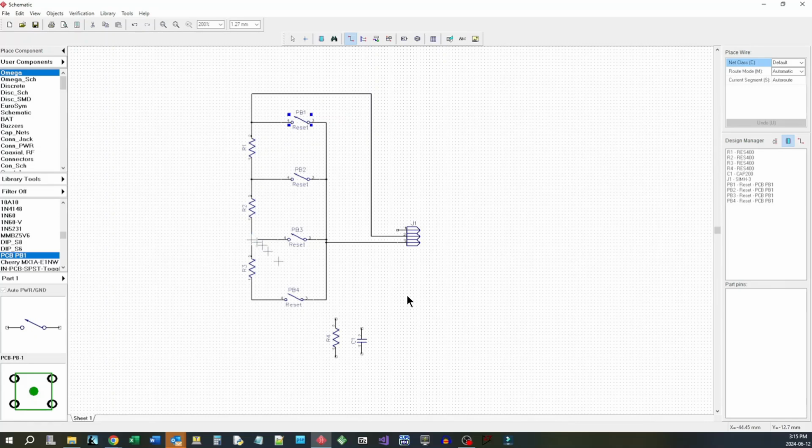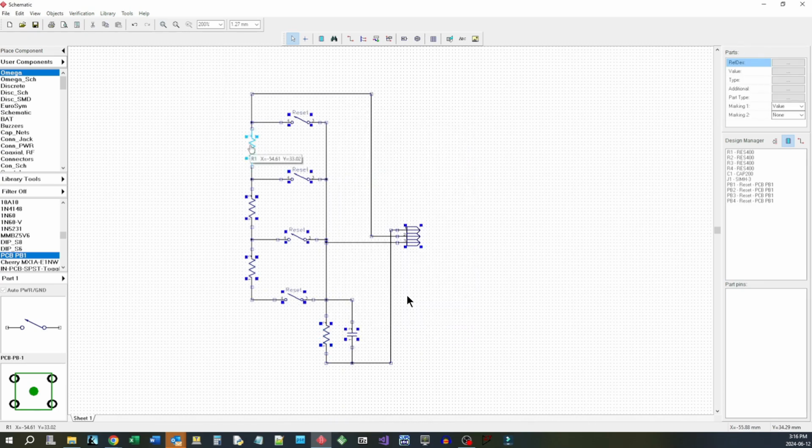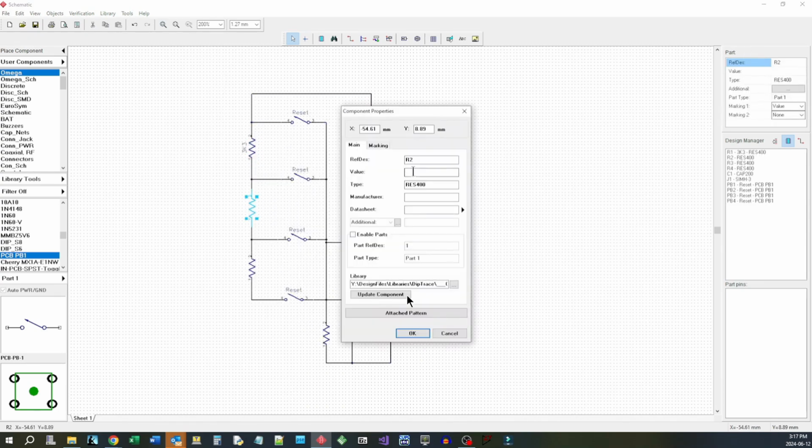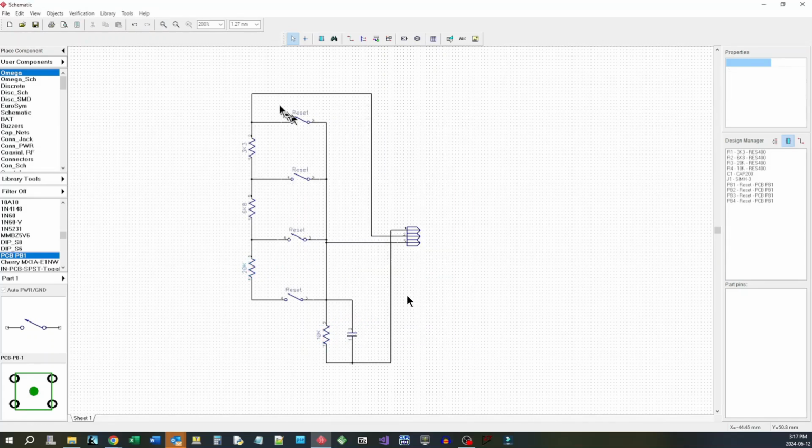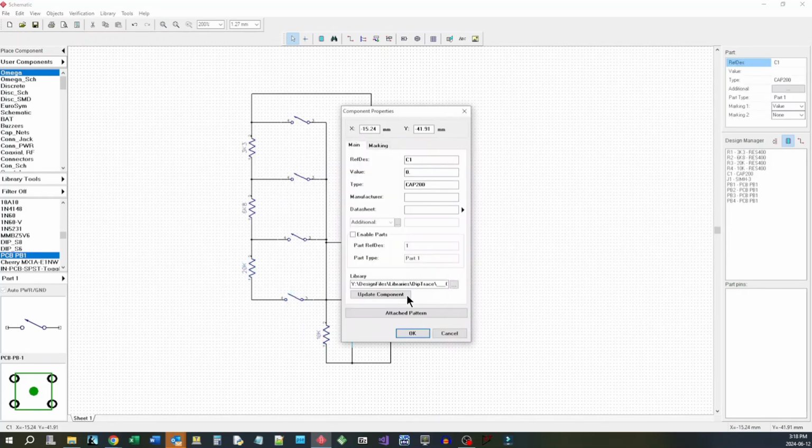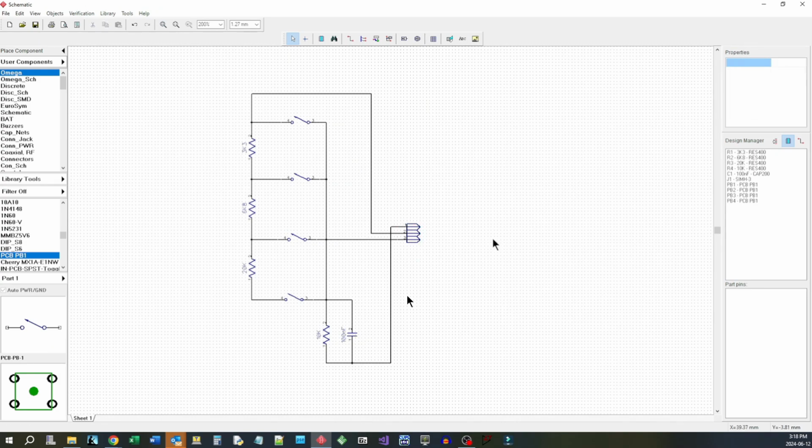I've done that before too. And lay everything out so it's a nice, easy to read schematic. You can understand it at a glance. And then we go and we set all the parameters around each of the components, their values, their names, how they're supposed to show up on the silk screen in the final PC board.